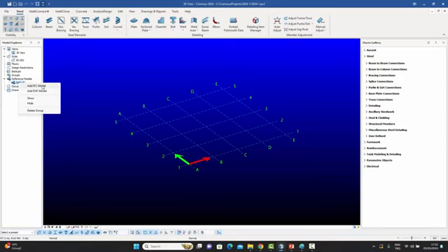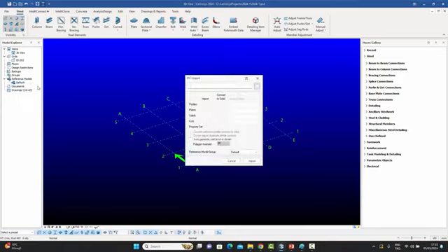Let's try the IFC model first. If you click on that, you see this IFC import dialog box, which is very familiar from the normal IFC import, so I'm not going to go into the details of what that means. You can see training videos regarding that. But let's click on these three dots over here so that we can select the IFC file. It also allows you to change the subgroup over here if you want to, but we've already clicked from there, so it's chosen that.